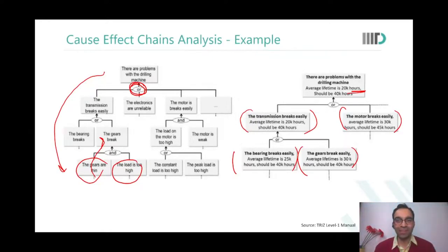Okay, so let's say write speed is less, so I will point it out to the low discharge rate or low charging rate of a particular MOS transistor, something like that. There could be multiple reasons. Why is the current of that transistor low? Because of sizing, you may say. Because VDD is low. The gate is driven to a low voltage, or because there is a small VDS. Multiple reasons. You see, there could be multiple, and these are all ORs. Yes, either of them could lead to this.